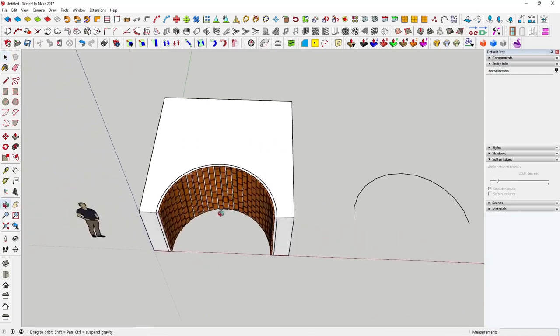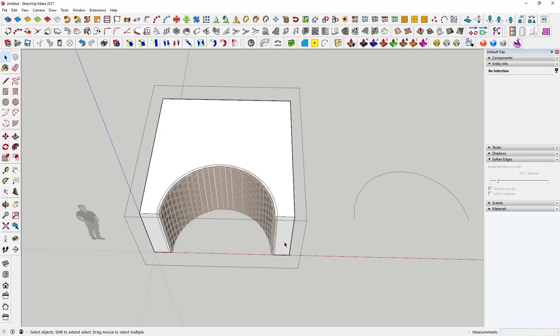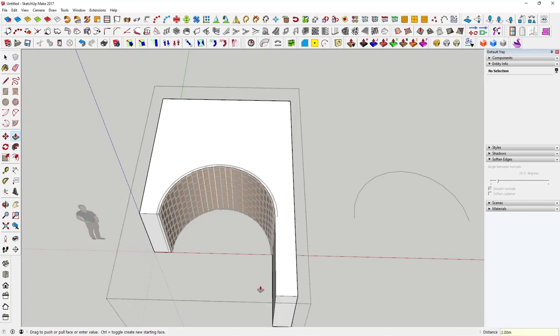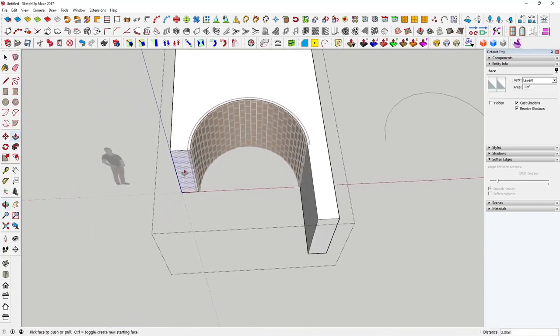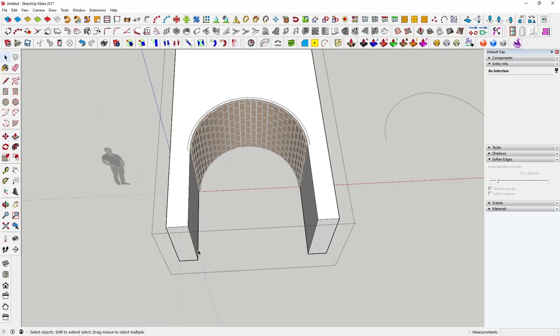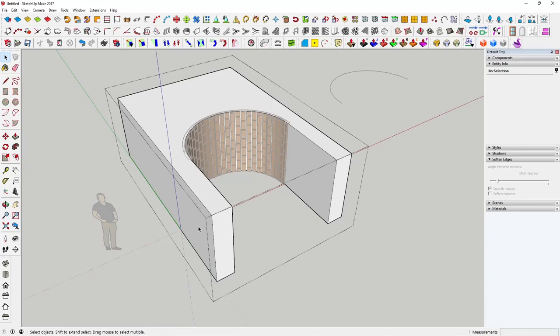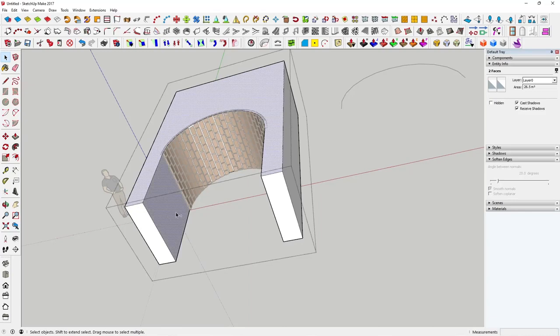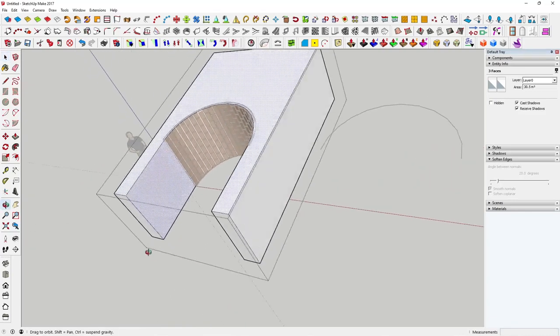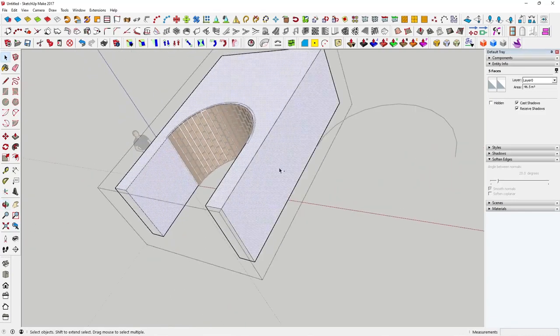So now I want to make a bit more of an arch, so we'll double click our cube, pull, say 2, gives us 20mm. Go to the other side, double click, and it'll pull it the same amount. We'll get our pick tool, and we want to control, pick, side, front, inside wall on both sides. So we should have all our walls highlighted there. Copy.